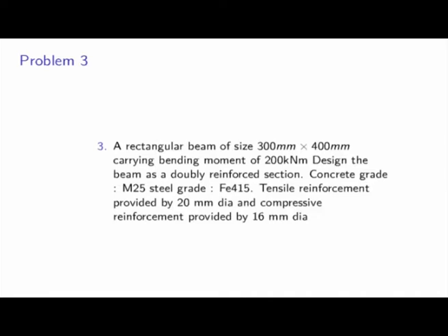In the very beginning it is decided whether you are going to use M25, M20, M30. For buildings generally we use M20 minimum, then M25, and we go to M30 also. If we consider bridges, there you will find we start with something like M30 or M35. Different cases we use that way.